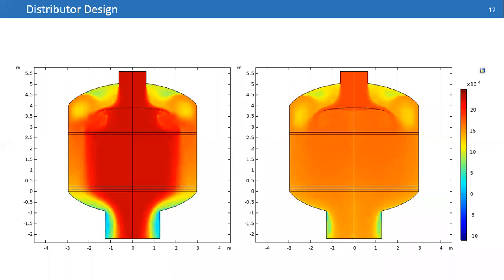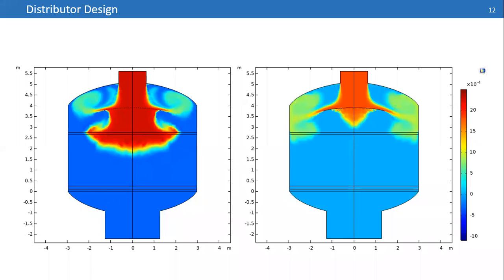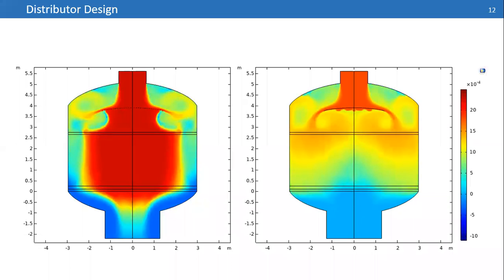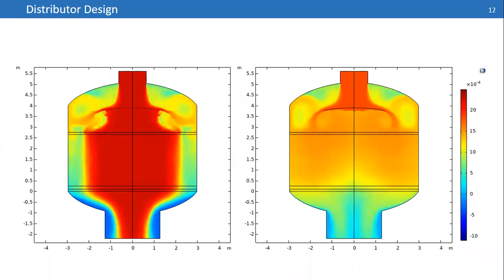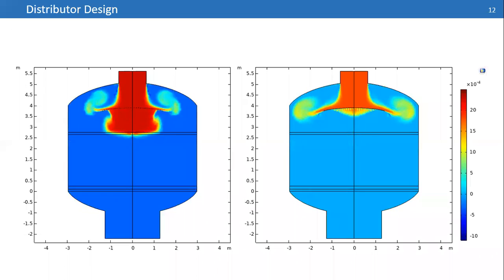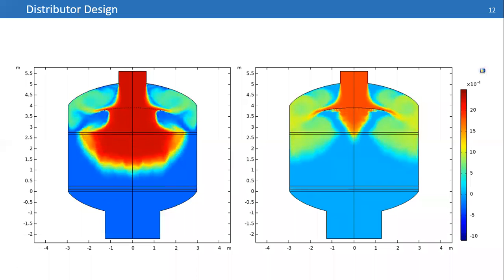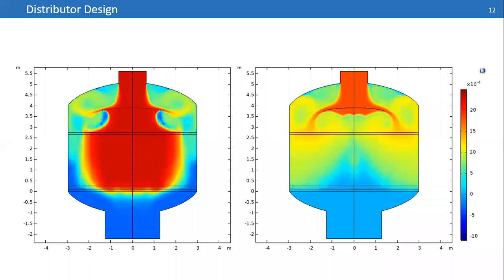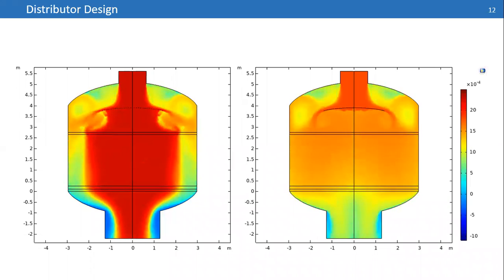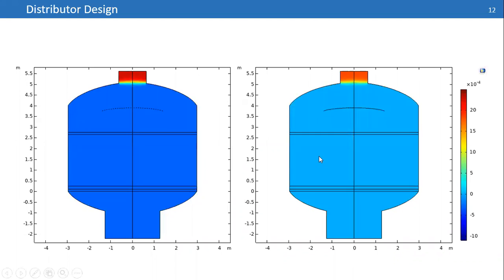But you are solving at the same time the mass transfer equation and also fluid flow, with diffusion and convection both coupled with fluid flow, since for convection you need to have the velocity of your fluid inside of your bed, and this velocity is going to be used for convection purposes.